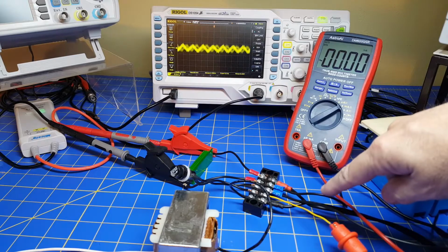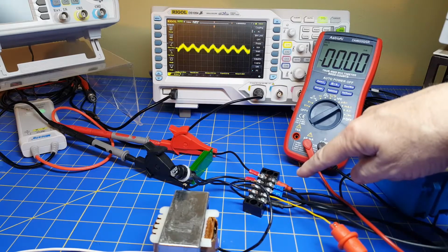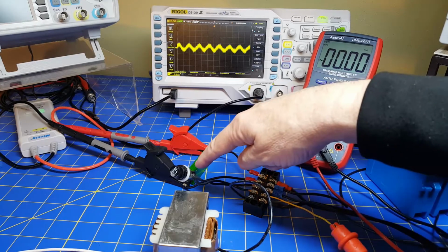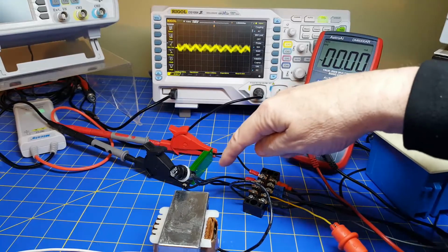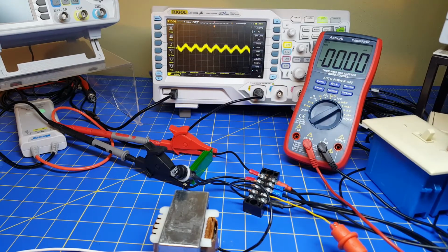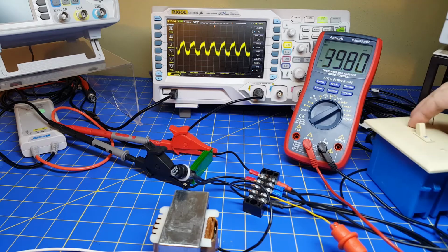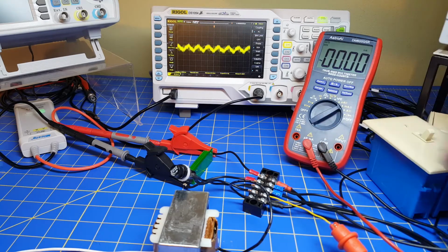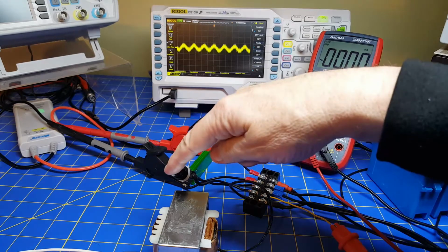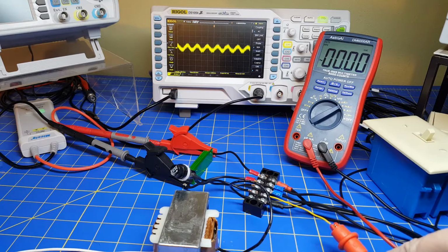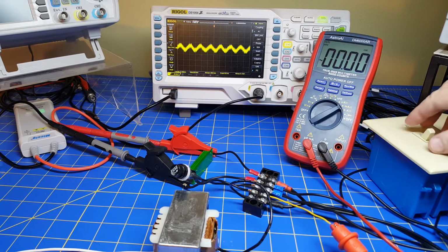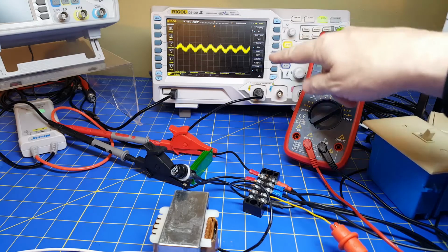So what I'm doing here is I've got my 120 volts coming in, as I described in the previous video. I encourage you to watch it. This red lead is the 120 volts coming in through the 0.5 ohm shunt resistor. I've got my differential probe going to the scope, and it's going out through this on-off switch, then through a fuse. This is a 0.1 amp fuse. From the fuse, it's going through my ammeter right here, and then coming back and going into the transformer.